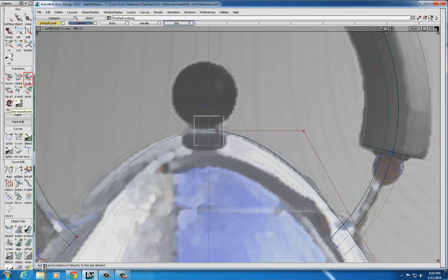But zeroing the transforms will set it up so that your axes reset for the object. So when we rotated the object, we rotated the axes. In this case, we went 90 degrees, so we don't need to worry about the object distorting if we scale it. So just setting them back to 0 resets the axes back to the world axis.